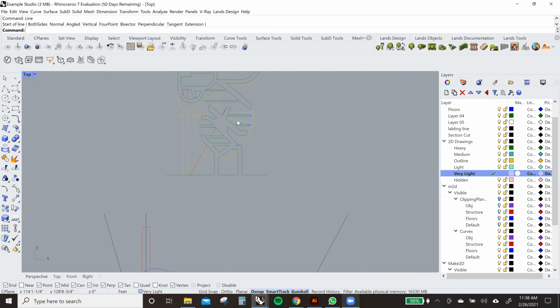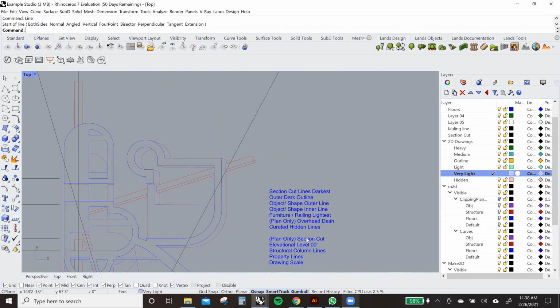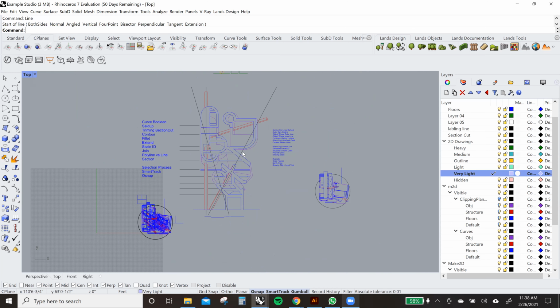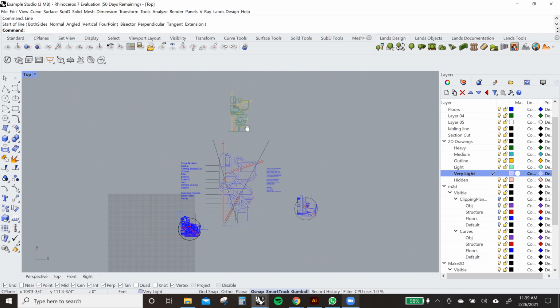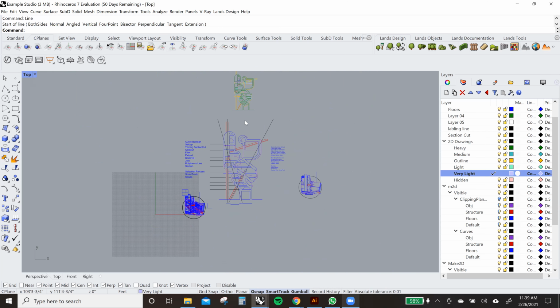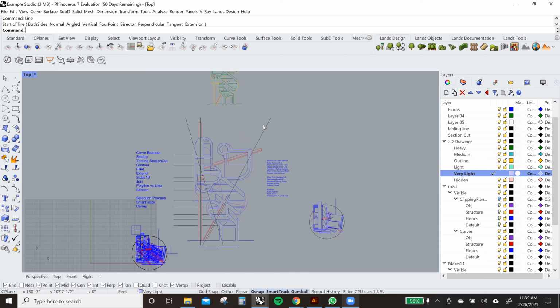So we don't really have hidden lines, do we? Not in this one. We're intentionally leaving them out. If you're on the edge between lots of hidden lines and no hidden lines, no hidden lines is the way to go. I think the next step is just to talk about the analytical lines. In the section, they're going to be your elevations and maybe structural lines if you have very specific structural columns. But if not, don't include them.